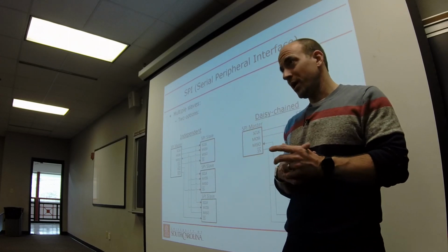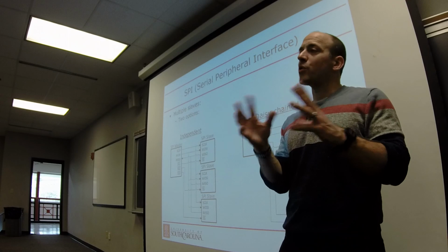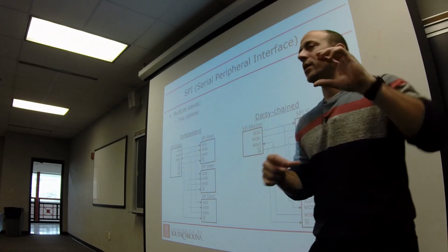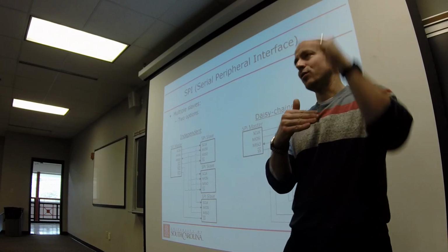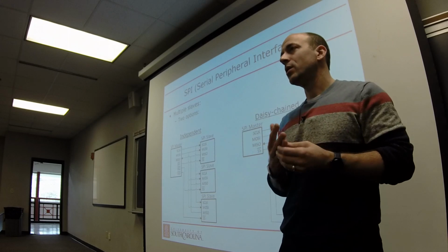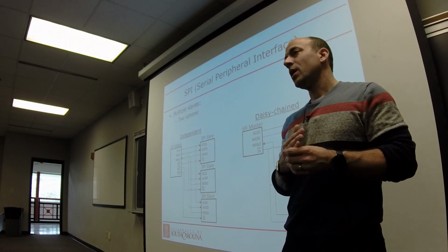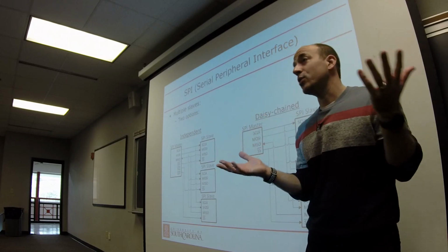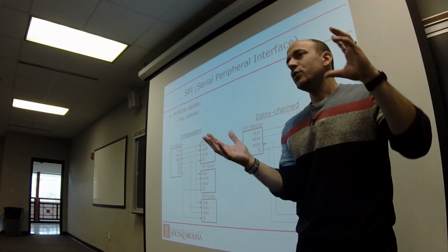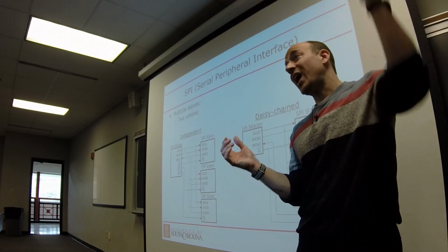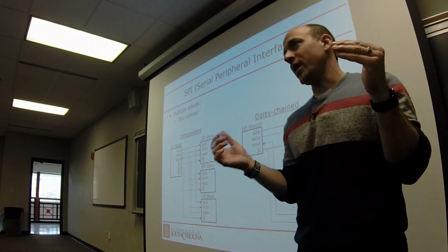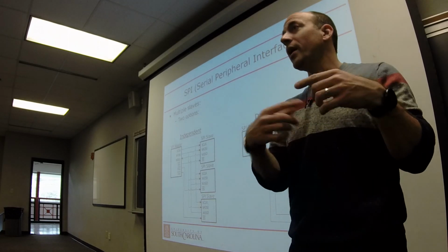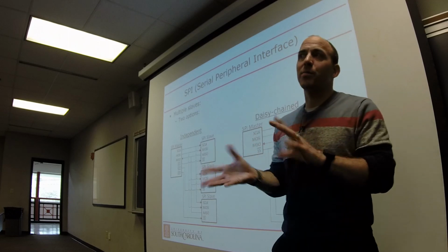You can use software PWM, meaning that you use the wait function. So you basically set the pin high, and you just use a _delay_us function to delay it to control how long it's high versus low. So there's 2 delays. 30% efficiency, it's only on for 30% of the time that it would have as a full cycle. So say your period was a millisecond. 30% would be you'd set it high and delay for 300 microseconds, and then you would set it low and delay for 700 microseconds, and that would be part of a loop. And that should give it the appearance of a 30% brightness level.